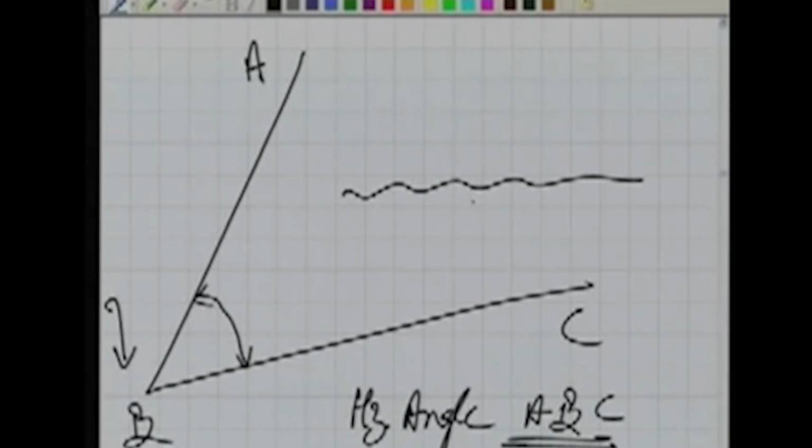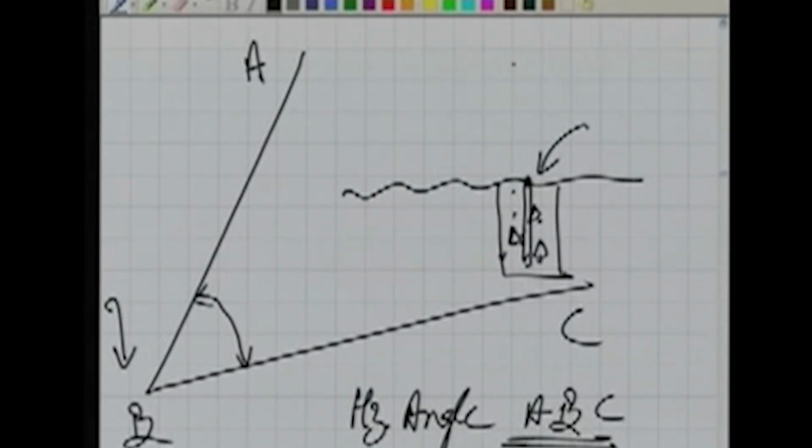Well, when we say traverse stations or survey stations, what do we mostly do? There in the ground, we decide to take a particular point as a traverse station. Generally, we put a concrete block, and in this concrete block there is an iron nail which marks the center of the station. So in the plan, if this is my concrete block, there is a nail, and the center of that nail is the station. So you can locate that center physically there.